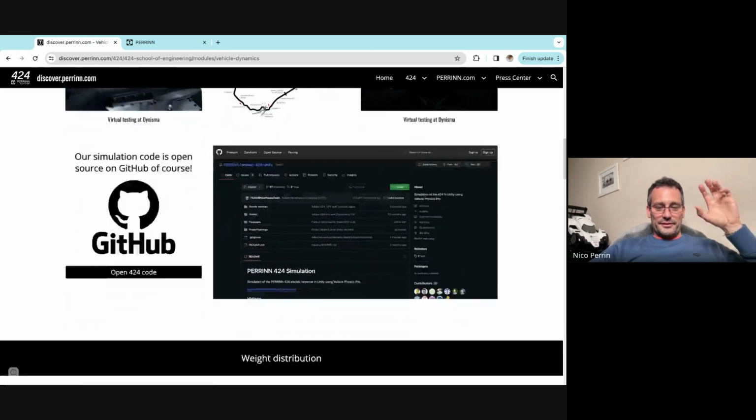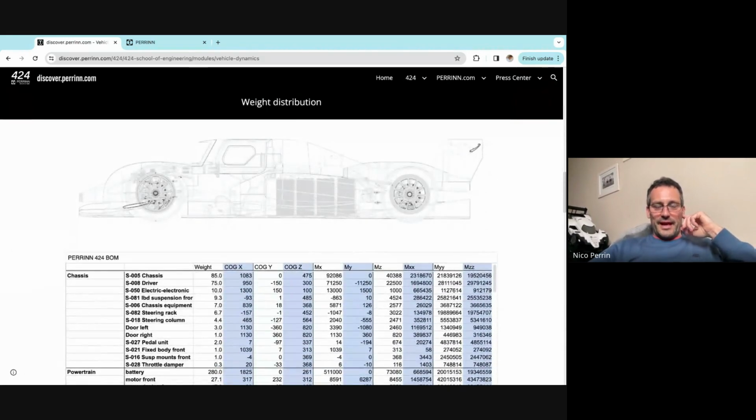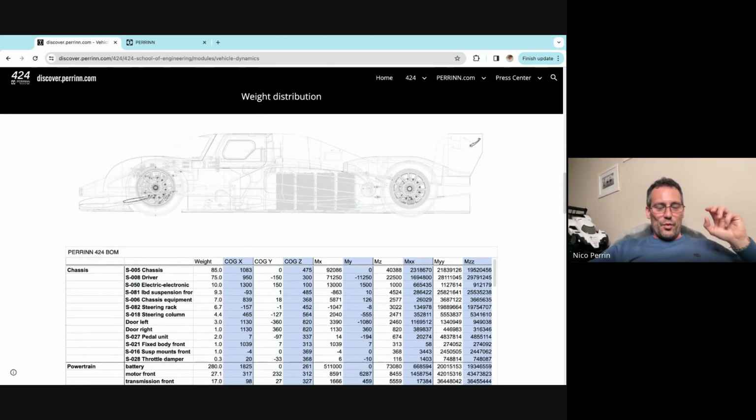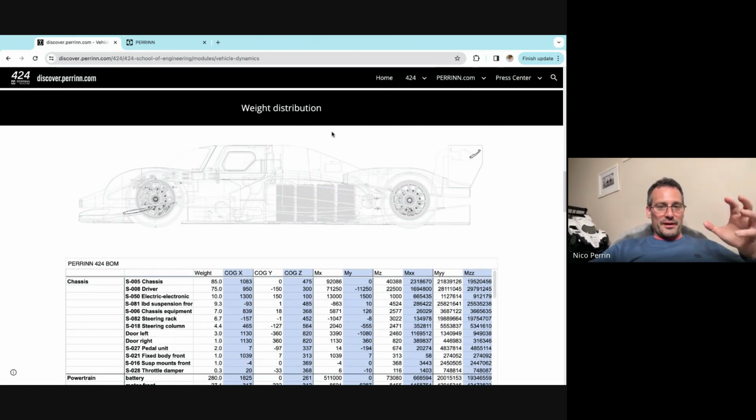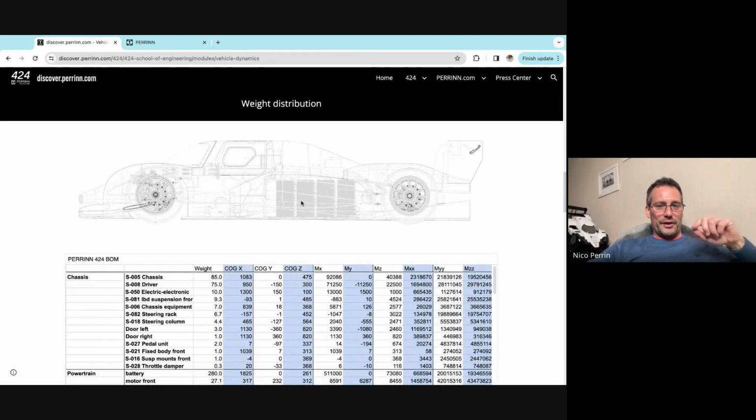We've looked at a lot of data from Unity. I want to break it down now into various aspects. One major parameter for the balance of a car is weight distribution. Weight distribution is front to rear weight. On 424 now, we found that the optimum weight distribution is 47%, which is about it. The center of gravity is roughly about there.